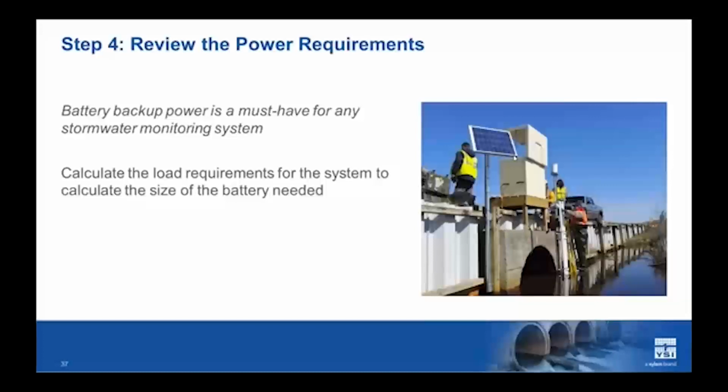And as we saw in the last example, really monitoring the power on your stormwater systems is really, really important because, boy, you don't want those things to fail in a storm because you forgot to change a battery. So understanding how much power you're going to need at the site, how you're going to get it there, how you're going to keep it charged, and keeping an eye on the power is going to be really, really important. I never recommend having single layer power for a stormwater monitoring system in particular.